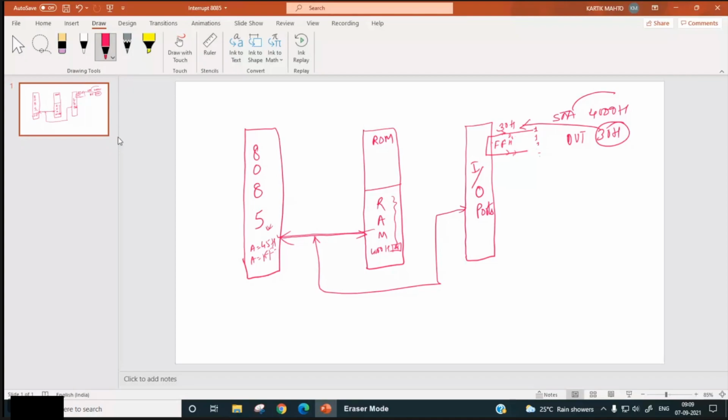And we discussed earlier how a single pin, any pin of a port, can be used for controlling some switches, like this. A 12-volt relay coil is here, so it can turn on the contact, and the contact may be given to a power supply and it may be used to run a motor.